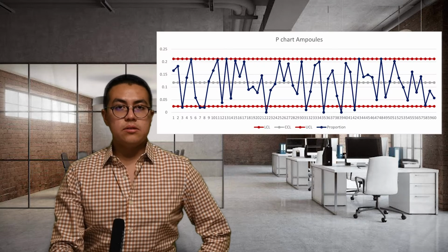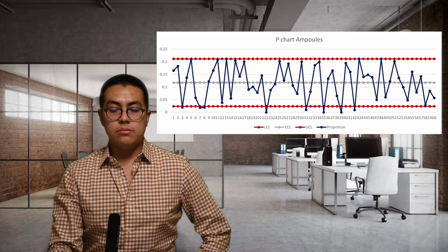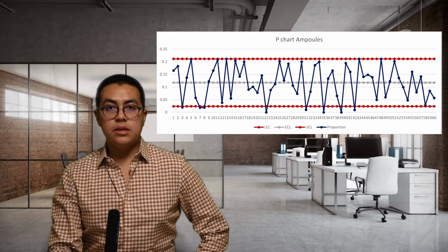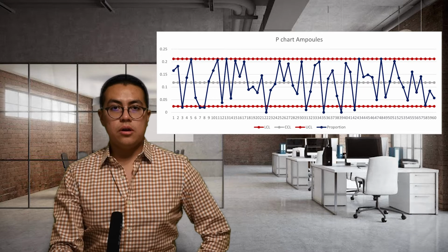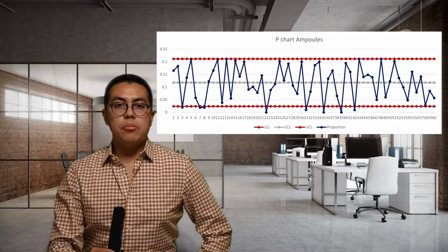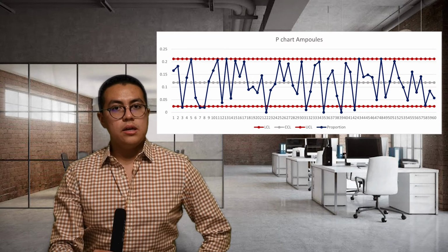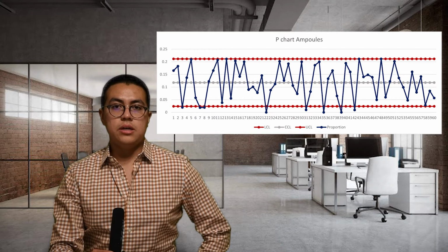Discussion. For our first step, we made the P charts for all three products that MediCrystal Co. makes. The first one was for the ampoules. So, as you can see in this graph on my left, there are many points that go outside of the lower control limit. This could be seen as something good since the proportion of non-conforming articles is lower, but since it falls outside of either of the limits, it's not ideal, and so it must be perfected.